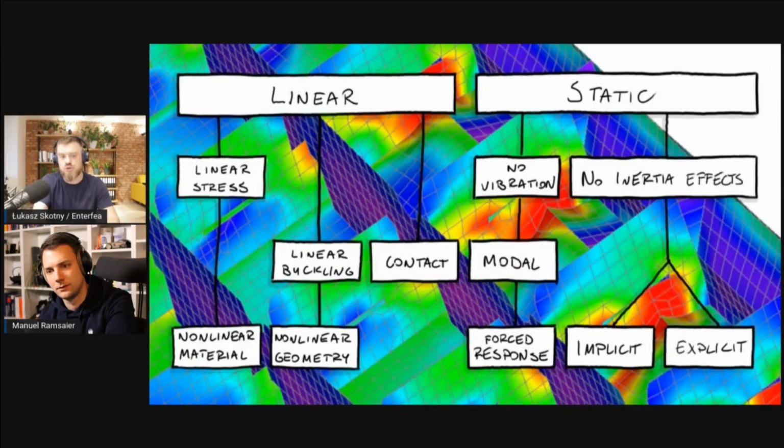The time step will be computed. It's effectively depending on your element size. The impact wave will travel through the material on the length of the shortest distance of your finite element. So you have very small elements. The smallest may have like 10 millimeters across or 1 millimeter. And then the impact wave is traveling like a few thousand meters per second. How much time does it need to fly through there? And this is the time increment. So it would be like 1 times 10 to the minus 7 or minus 8 maximum. So the time is super small.